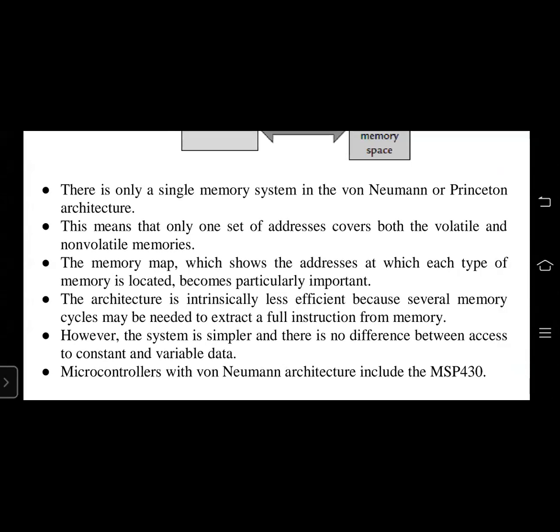Now, the architecture is intrinsically less efficient because several memory cycles may be needed to extract the full instruction from the memory. So of course, at a given time point, you cannot fetch the data and instruction. So obviously the number of cycles to execute a single instruction, and so to execute the entire program, will be more than in Harvard architecture, because the number of cycles to fetch the instruction and to fetch the data will be more.